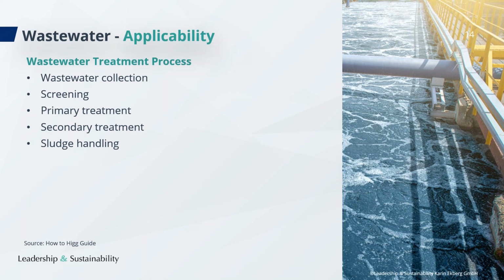But it may be, for example, if you are treating only domestic water, that the sludge is not hazardous. And so you always need to check what the regulations are locally in order to define what is a hazardous sludge and what is not hazardous. And the sludge is then disposed of, as I said, and the filtrate water is fed back into the wastewater treatment plant.